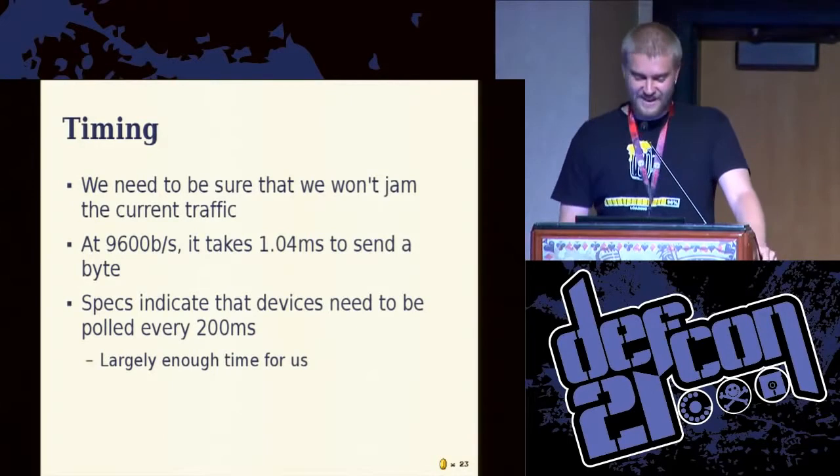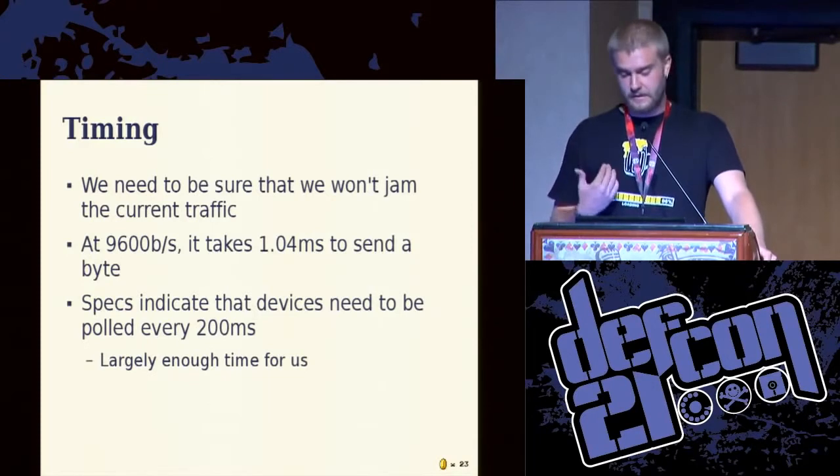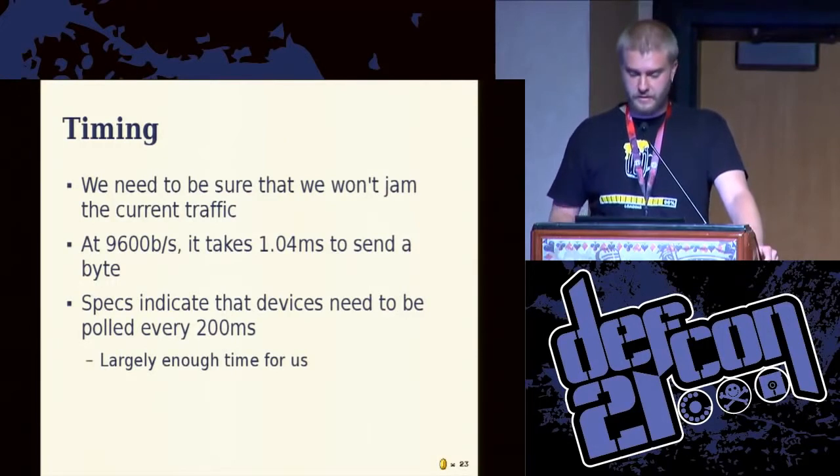I won't say more. So you really have to check for the silence, and in the specs it's indicated that the device needs to be polled every 200 milliseconds. So as the packet needs about 8 milliseconds to be sent, there's normally enough time for us to do it.